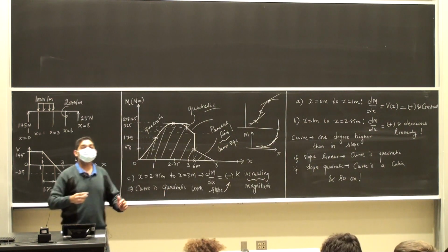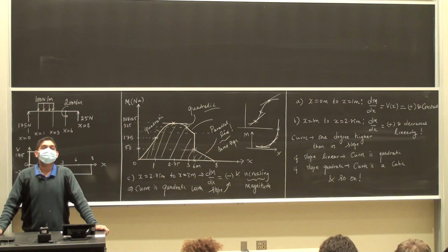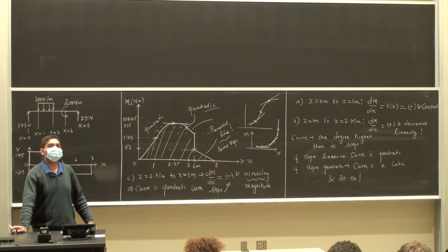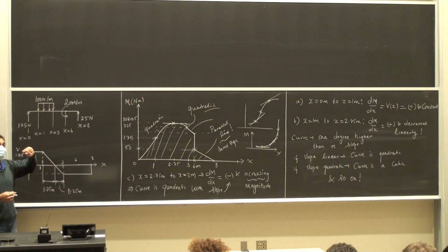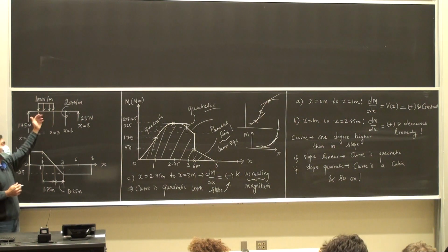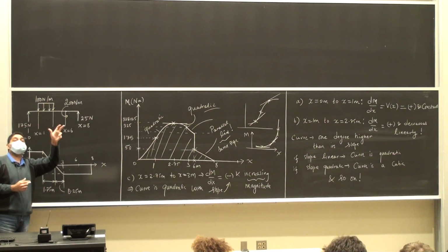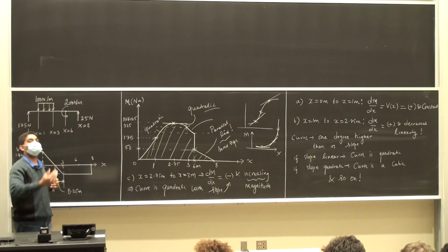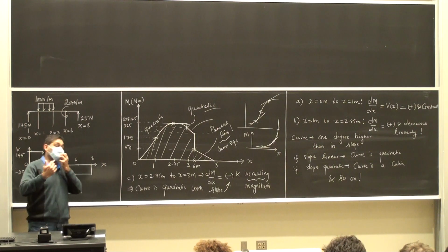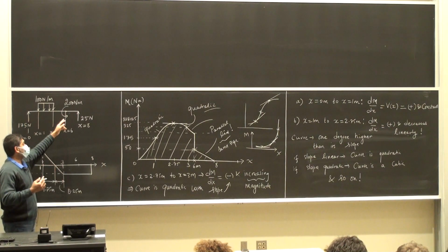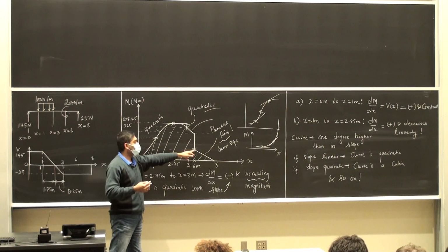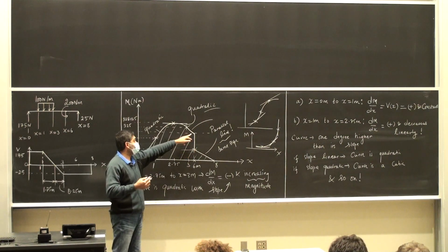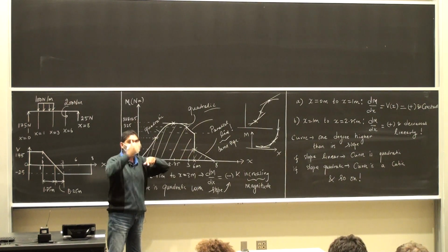Yes, sir. Question. So for the bending moment diagrams, will the counterclockwise couple moments always be negative? Yes, that's what we derived a couple of lectures back, and that's something that I pointedly suggested, that it is against our common intuition that if I have a clockwise couple moment, it causes a positive jump in the bending moment. If I have a counterclockwise couple moment, it causes a negative jump in the bending moment diagram. And we also calculated the value here last time, and we found that it was dropping from 250 Newton meters to 50 Newton meters. Yes, so straight down.